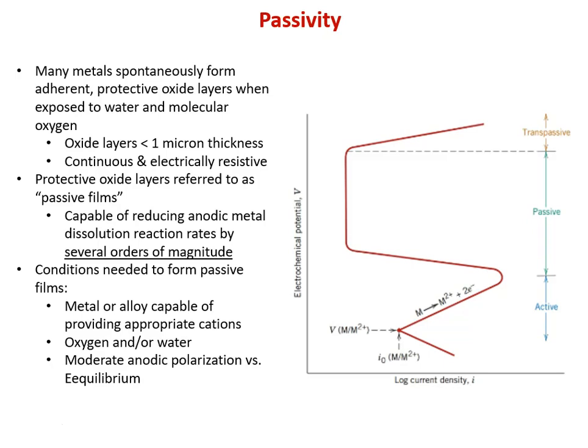So if we have a metal system corroding, but instead of being zinc, maybe it's stainless steel or nickel or titanium, we would start out at equilibrium where we're not driving the corrosion through the external circuit, and you would have our exchange dynamic equilibrium of that metal with solution, and that's the I0 that you see at the little point down near the bottom of the diagram.